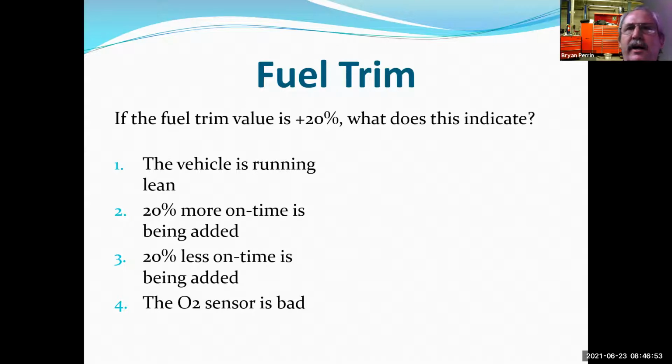I have a case study where I'm actually adding 40% injector on time, but since the computer hasn't run out of fuel control, it has more, and we could prove that by looking at the data. That means we're still in fuel control because it's still able to switch the oxygen sensor rich, lean, rich, lean. Well, if the oxygen sensor goes rich, we're not really running lean.